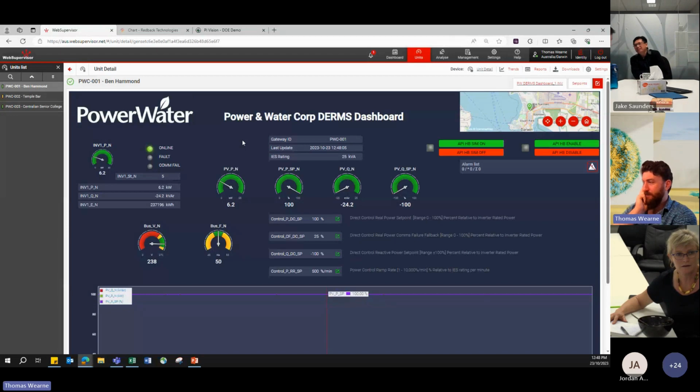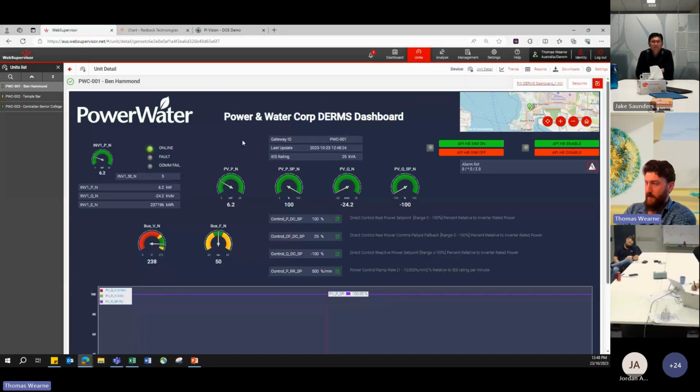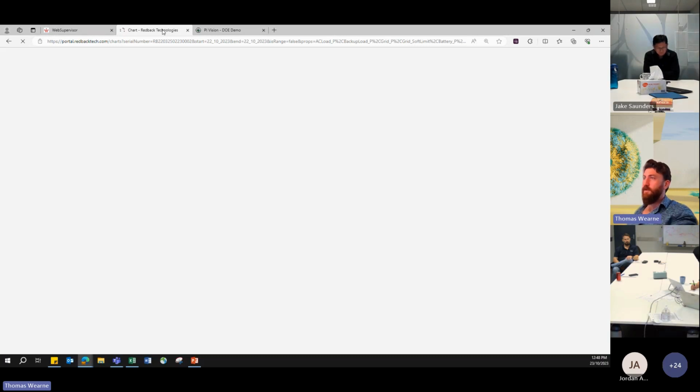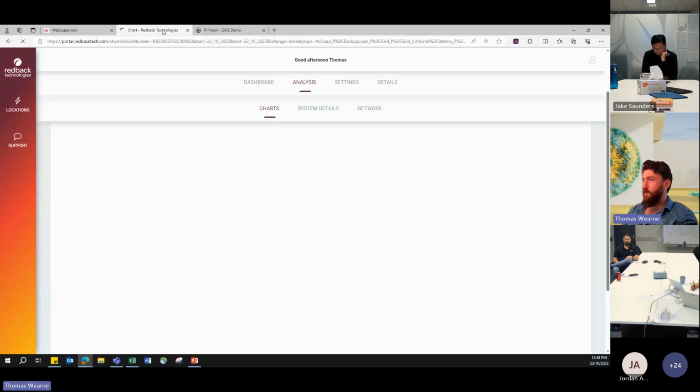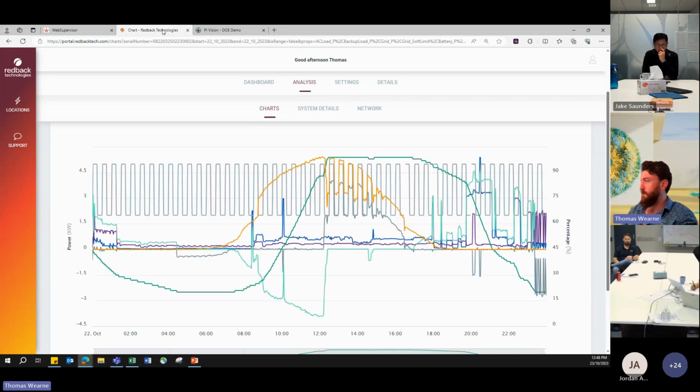Most of them, certainly. So in this case, you're talking about local, they call it Modbus TCP control, using an open protocol called SunSpec, which most inverters speak. We didn't find any example of an inverter that we couldn't control with the ComAp solution, but there are some exceptions, and one of those exceptions is Redback, which we talked about previously. So you do get the odd inverter that doesn't want to be controlled locally by somebody else's hardware, in which case the version of control is this API or internet-based approach, which you can also do.